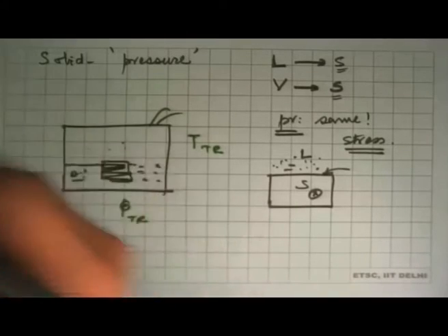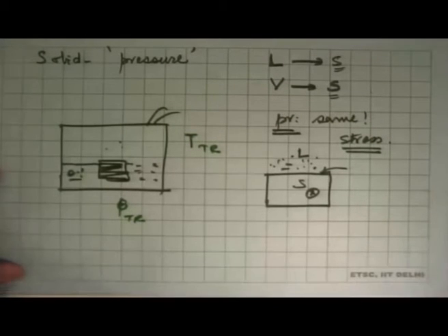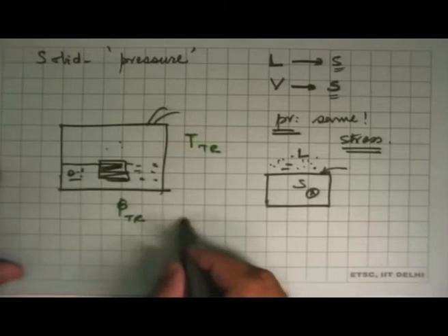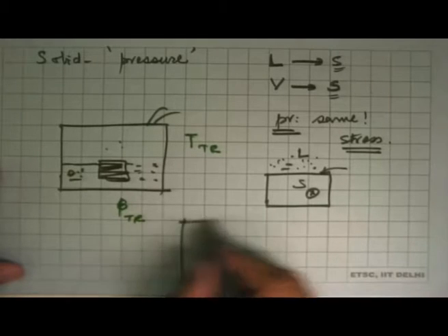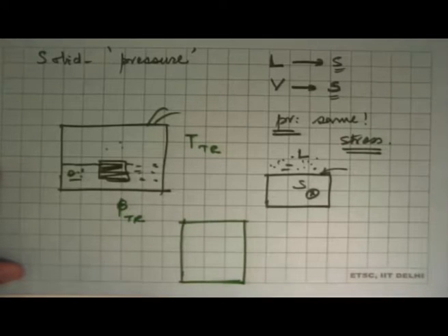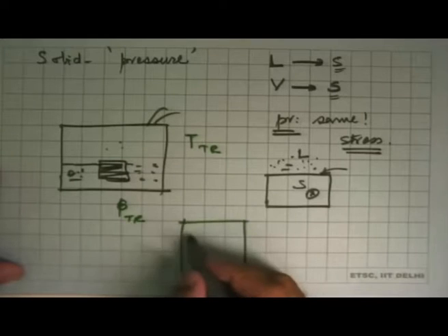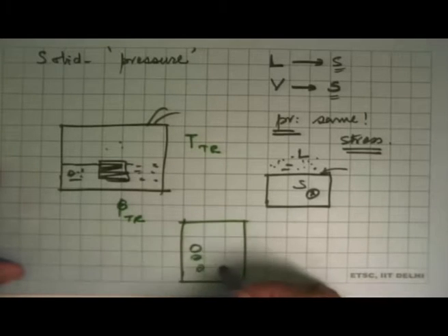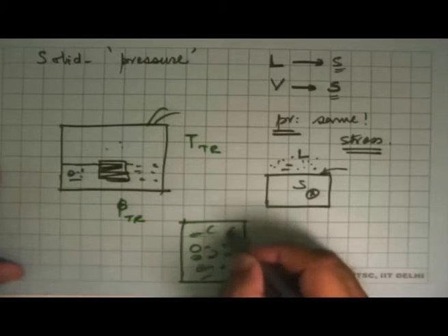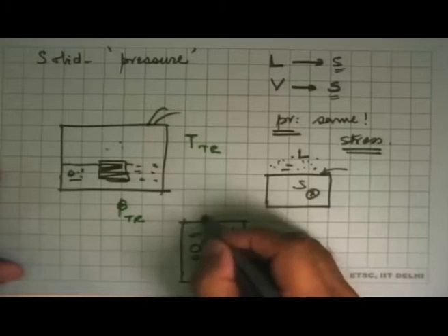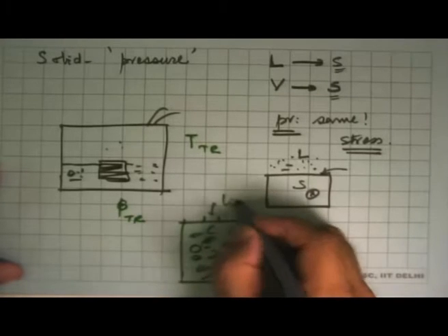And we exploit this in one very important way, not in thermodynamics but in all measurements of temperature, especially in heat transfer. What we can do is, and you can do this small experiment yourself, take a thermos flask, push crushed ice into it, pack it as much as you can, and then pour a little bit of tap water in it.